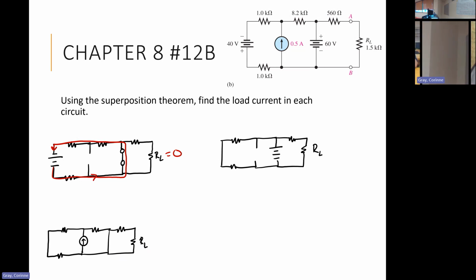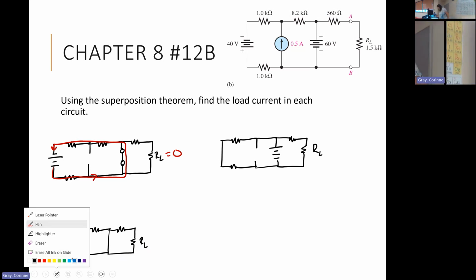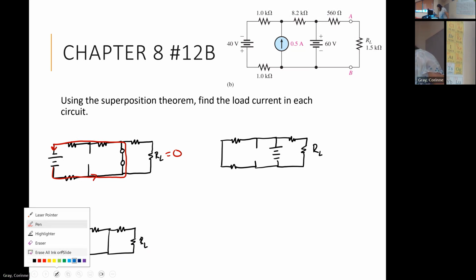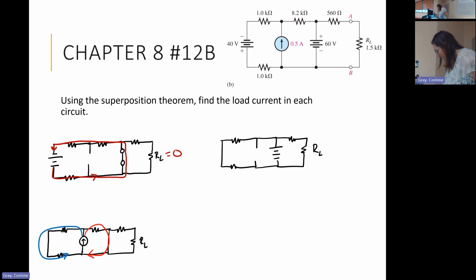If I look at the other way, it's going to come through this here. It's going to reach this junction, and again, there's a 0 resistance path. It's going to take that, so all of it's going to come through and down here. And once again, I will have a situation where RL is equal to 0. We have this path or this path, we have another 0. So for two of the three sources, they do not contribute any current through RL here.